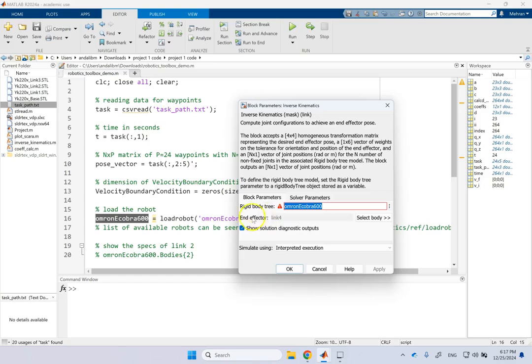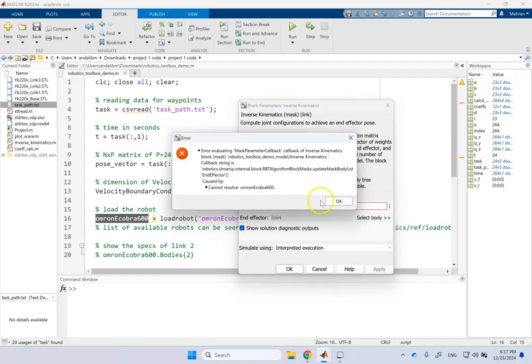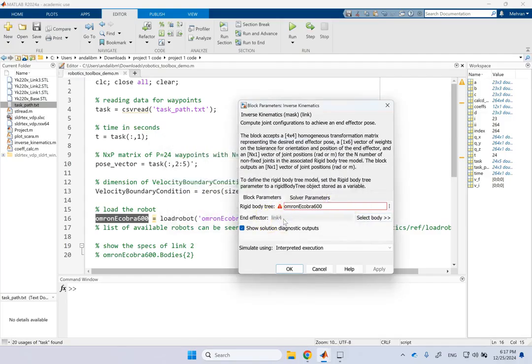And you can pick the end effector to be any of the links. So here is link 4. I show you, you can change it. So this one is there. Then it performs the inverse kinematics in general numerically. It does perform it numerically, so it can apply it for a lot of different robots. And the way that it does it is either with a version of gradient descent algorithm, which is called BFGS, or with the Levenberg-Marquardt.